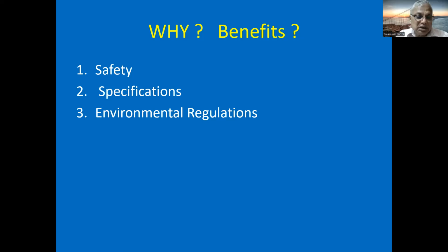For example, if discharging a liquid effluent into a river, the regulations would have specified the limit of the pollutant components in that. Similarly, stack gases may consist of noxious gases, CO, SO2, etc. So the regulations mandate that these components should have a limit. To ensure that these regulations are complied with, we need process control.